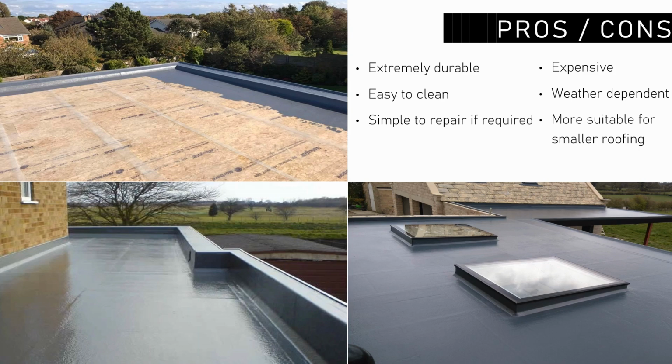One limitation of the system, however, is the cost comparison to other flat roofing methods discussed. The system is also very weather dependent and cannot be installed in wet conditions. Due to the location of Quayside Tower, the GRP roofing system may add unnecessary delays on the project due to the weather. Despite the system being used on larger projects previously, the system was traditionally built for smaller construction, and Quayside Tower may suffer major drawbacks in the system if this is used.